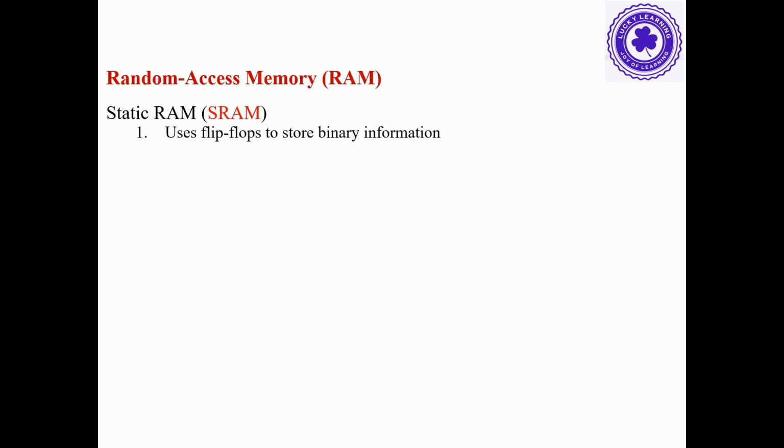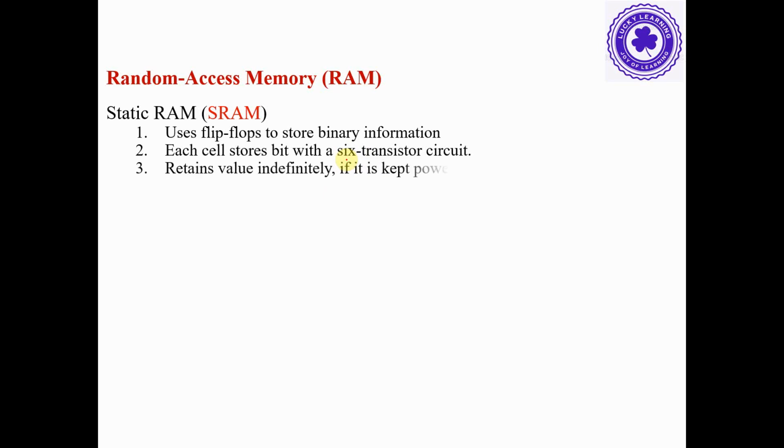Static RAM uses flip-flops to store binary information. A flip-flop is a 1-bit binary cell that is used to store binary information in the RAM. Each cell stores a bit, and that cell is made up of 6 transistor circuits, and it is going to retain its value indefinitely if it is kept powered.